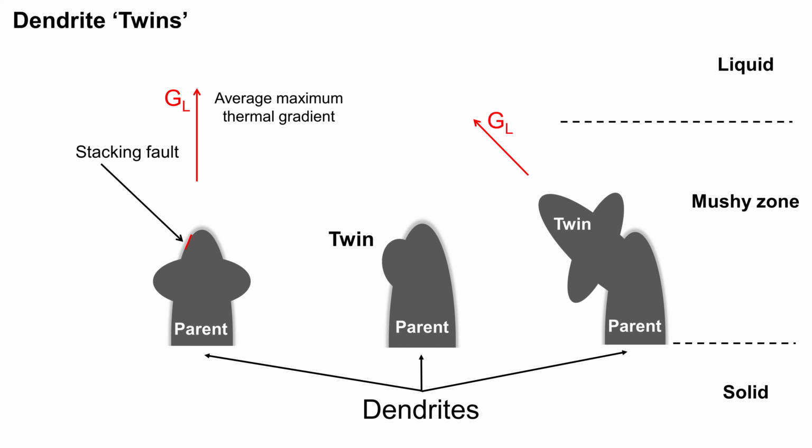Should the solidification conditions promote the formation of these stacking faults more regularly, there would be a constant disruption of growing dendrites in the liquid, and each stacking fault-induced grain would continue to grow into equiaxed grains, presenting no visual evidence they ever existed in the completely solidified metal at room temperature.